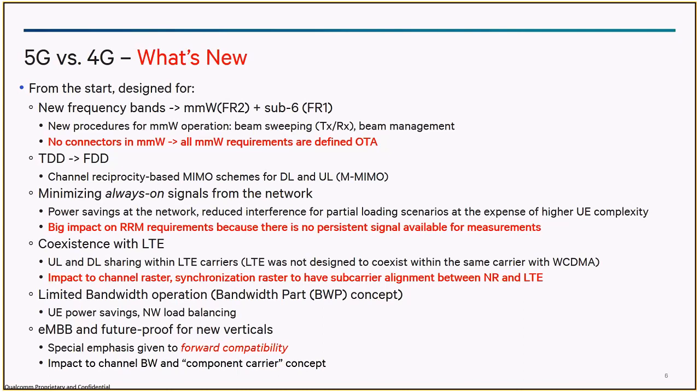This way, the number of UEs that can be supported per base station increases 4 times compared to LTE. And on the downside, for a UE, we have to support a 400 megahertz bandwidth in a particular band, but then you could be limited to one particular 100 megahertz bandwidth.